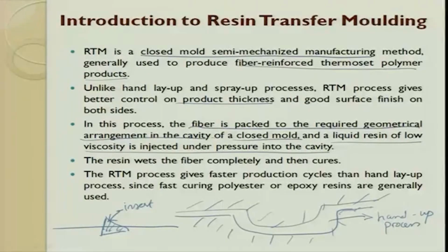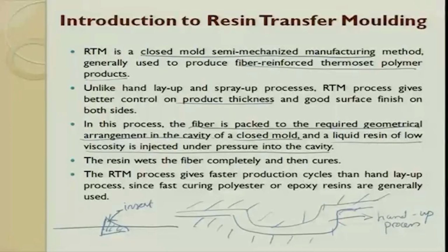When I said flow through the cavity, you can keep changing the flow, that means to say increasing or decreasing the pressure. You can allow it to happen of its own, or you can pressurize, that means to say you can inject liquid resin. So, injection can be done from the nozzle side, or you can do it on the other side, in which you apply a vacuum and suck it. So, when you suck it, what happens? The flow happens. And the other advantage when you do vacuum is that it spreads uniformly. So, depending upon your requirement, suppose it is a very large area, we always try to pressurize and inject the liquid inside. Okay.